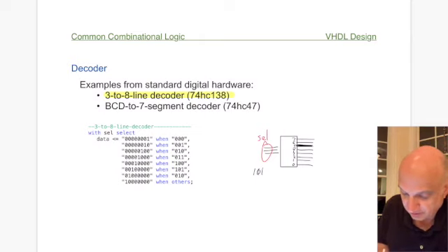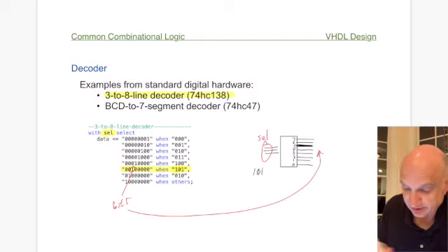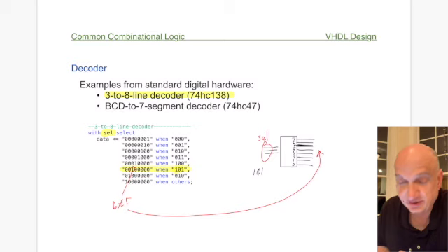And so every input on the select line is checked, and when it's something like a 5, it will cause the outputs to activate in such a way that, in this particular case, bit 5, that's the same as this one, gets activated. And so we do it for each one of the possible 8 codes, and we've covered all our bases in a single data flow statement.